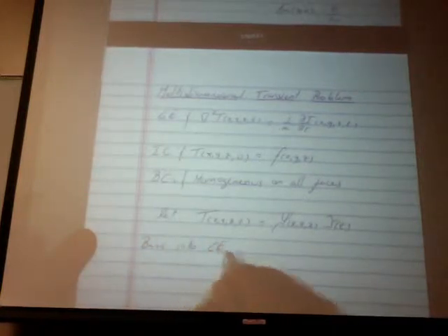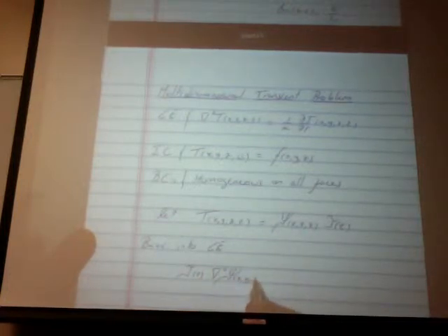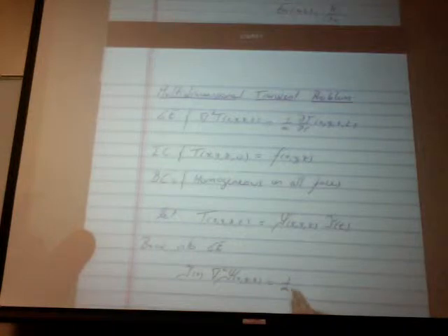So back into the governing equation, we get tau of t times the Laplace of psi of x, y, and z is equal to 1 over alpha psi of x, y, and z times tau prime of t.